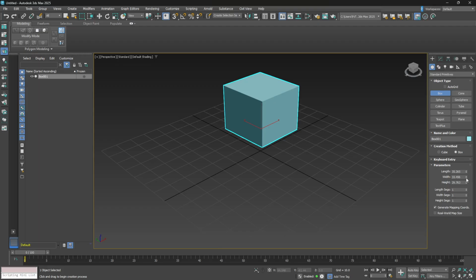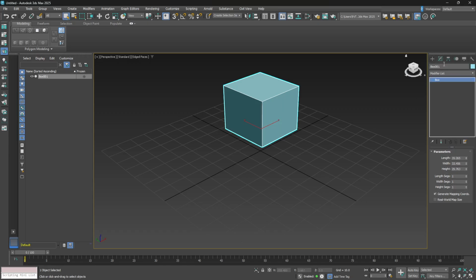When you create cubes here, they're basically non-destructive at first. You can change things like height and width segments. We already created a cube, so it doesn't update that necessarily, or does it? We can't see the edges right now, so you hit F4 and you'll see we can't actually change those here. This is just one place you could do that, but you can do it under the modifier panel as well. You'll see it's a box, and we have all the options available to us there too.